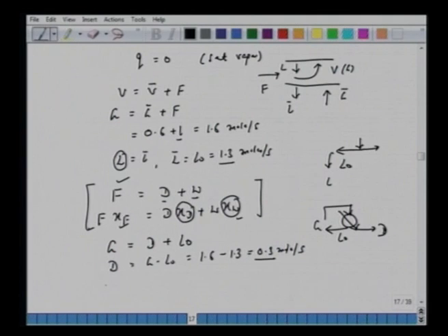How about for the bottom column? We have L bar split into two, W plus G bar. So W equals L bar minus G bar. L bar we set the same as L0, 1.3. G bar is the reflux which is sent back from the reboiler as reflux vapor, which is 0.6, so W is 0.7 moles per second.